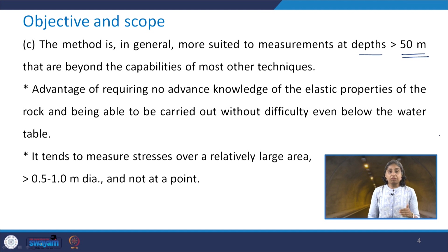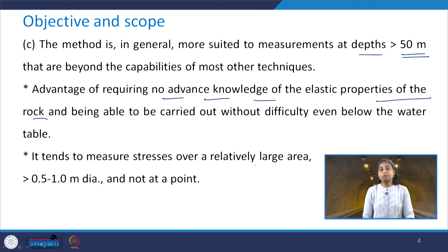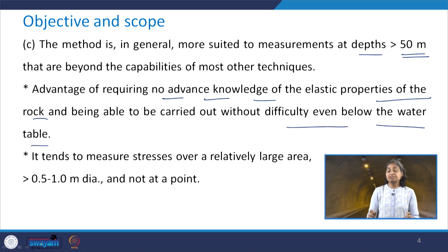The advantage of requiring no advanced knowledge of the elastic properties of the rock, and being able to be carried out without any difficulty even below the water table, is an added feature of this test. It tends to measure stresses over a relatively large area, which can be more than 0.5 to 1 meter in diameter, and not at a point.